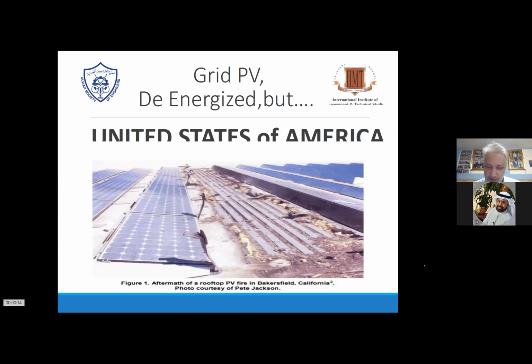We also had some fires, which is also known, actually starting after the system was de-energized. So in some Walmarts and in some malls, the system was put down because of some unmatched connectors. Most of the problems, I would say 70%, are related to connectors. So although the system is de-energized, maybe by AC or by a stop switch, the DC was always on.